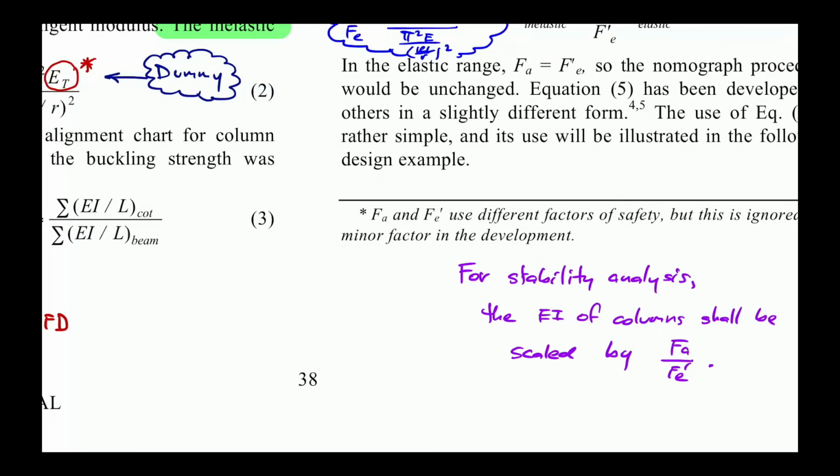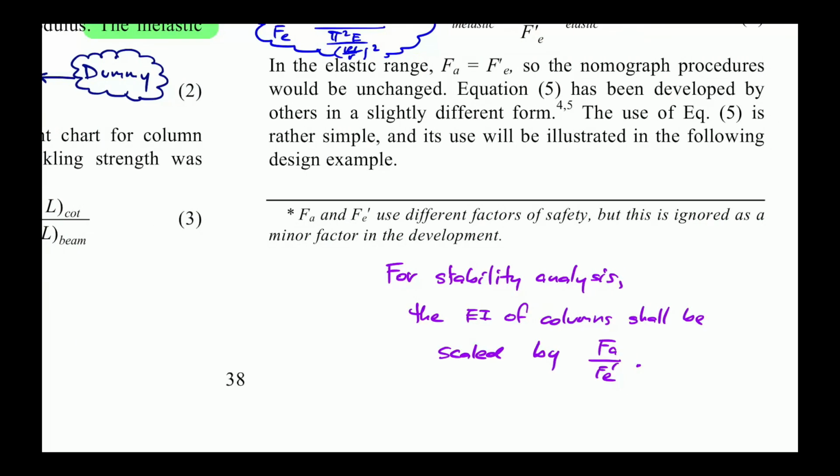We can run structural analysis, and then we can do the iterative solution as well. You can see the nature of the modification of the G values. It is just the stiffness modification. That stiffness modification gives you the G, the inelastic G. Inelastic G is used to compute the K. So basically, if you look into the framework, it is pretty much the same as running a full-fledged nonlinear geometric structural analysis. You just turn on nonlinear geometry, and then you run the first analysis.